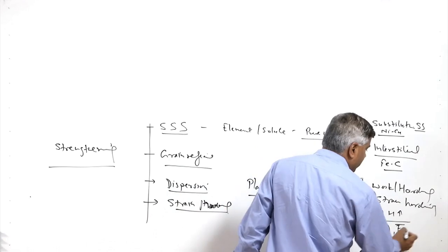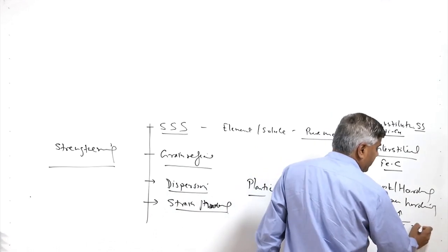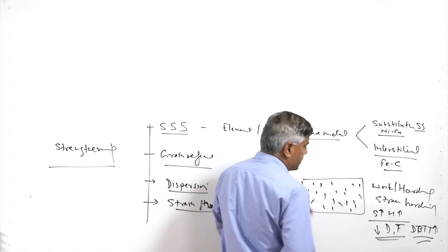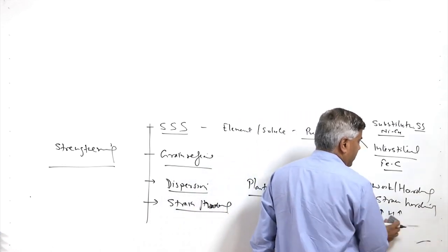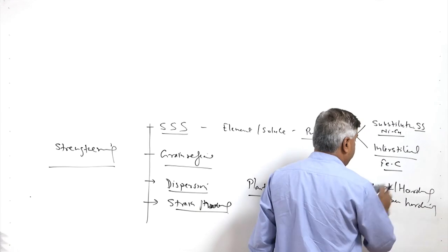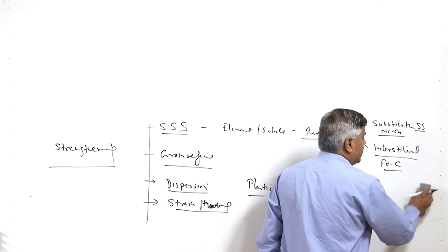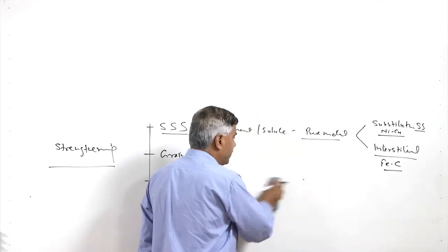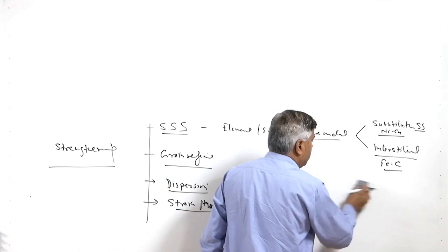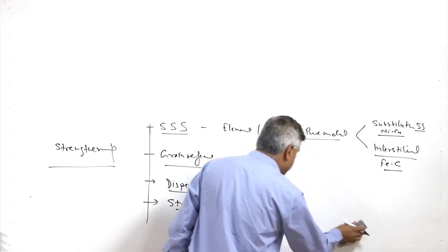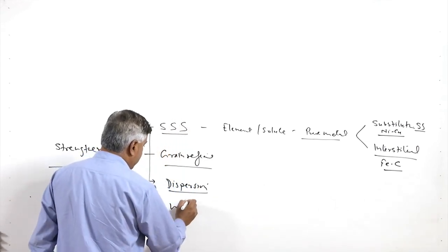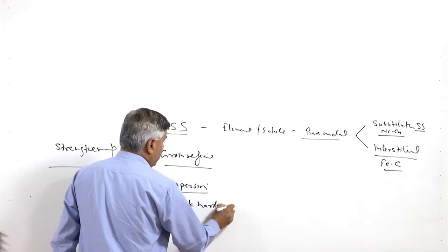Also, the ductile to brittle transition temperature, DBTT, is increased when cold working, the plastic deformation for strain hardening or work hardening, is applied. The ductile to brittle transition temperature is the temperature at which there is a sharp drop in the toughness of the material, and below which it tends to behave more like a brittle material. So, work hardening or strain hardening is another approach.